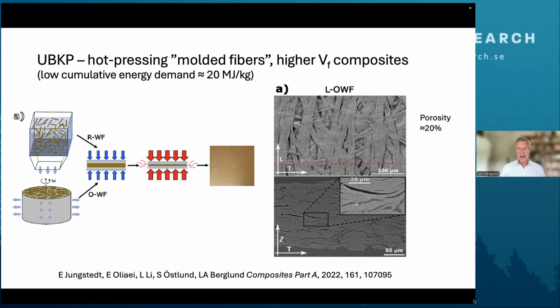But I think in liner production, for instance, you also have substantial orientation, and that's not so far away from dynamic sheet forming results. We then hot press, and we utilize the lignin in the cell wall of unbleached fibers. So the lignin hemicellulose mixture functions as a liquid binder in these materials.